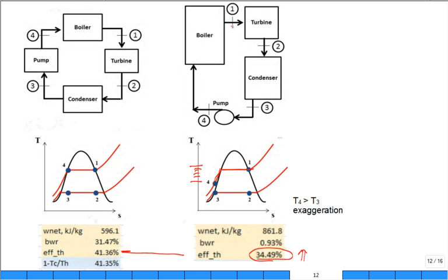It's like I'm coming into this boiler right here. What temperature am I coming in at? Oh, about 60 degrees C. What temperature out? Around 300 degrees C. Think about it going along a path. Well, it's got to get to 70, then to 80, then to 90, then 100, then all the way up. Then finally it can start changing phase from saturated liquid, 10% quality, 20% quality, all the way to saturated vapor.